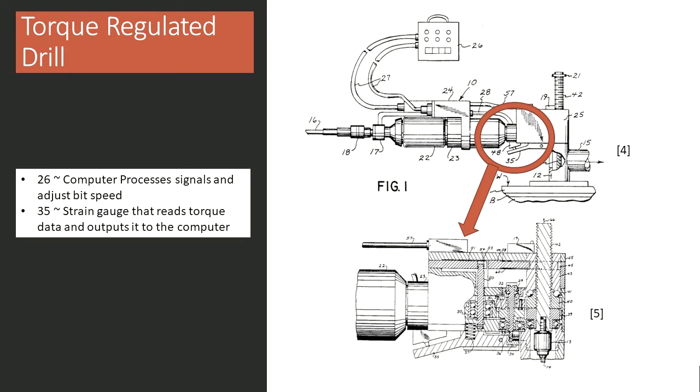As a bolt is being depressed into an assembly and tightened, the torque will increase little by little. Once the target torque is hit, that information is sent into the strain gauge, and that comes out of the strain gauge as a voltage, and the controller knows that the target torque is hit and cuts power to the drill until a worker releases the trigger and pulls the trigger again for the next bolt.